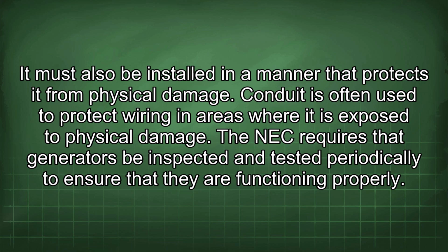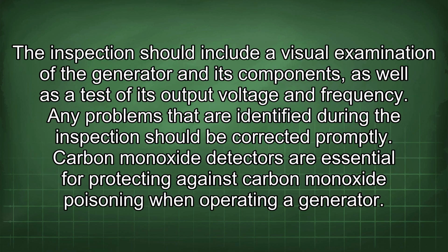The NEC requires that generators be inspected and tested periodically to ensure that they are functioning properly. The inspection should include a visual examination of the generator and its components, as well as a test of its output voltage and frequency. Any problems that are identified during the inspection should be corrected promptly.